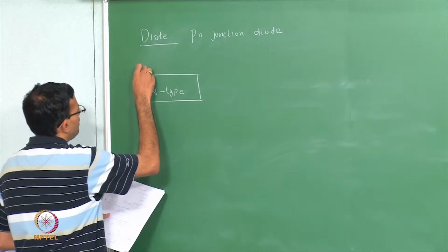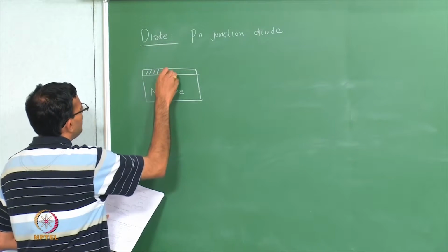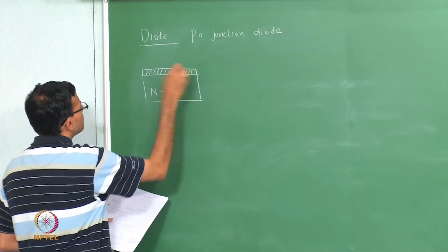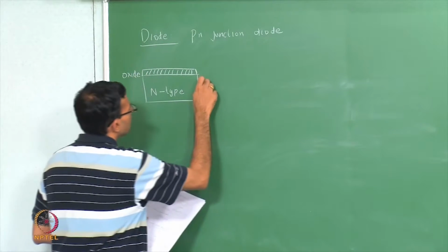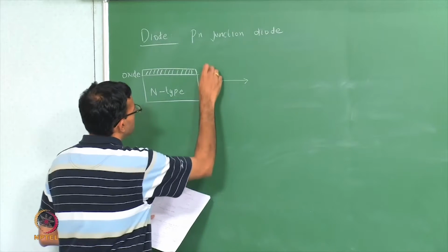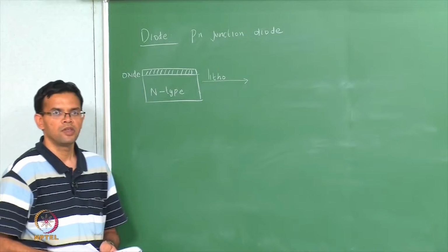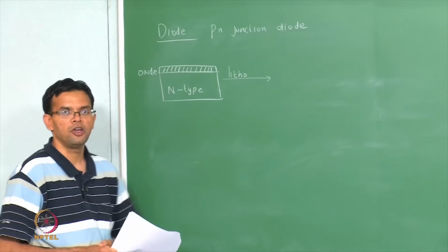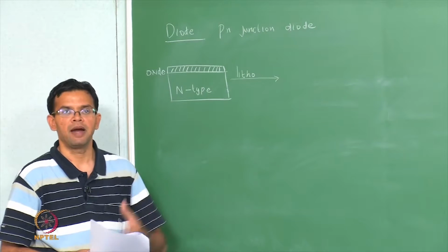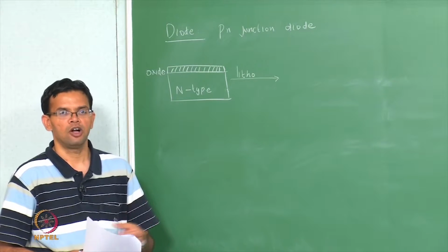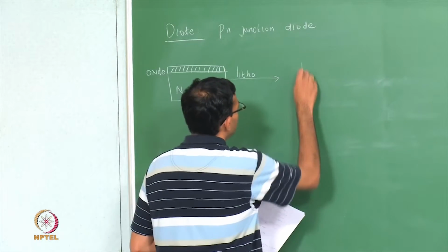So, for example, let us start with a substrate with an oxide layer. We can do lithography in order to open a window in the oxide layer. This is done by using a particular pattern and then doing some sort of dry etching to remove the oxide.